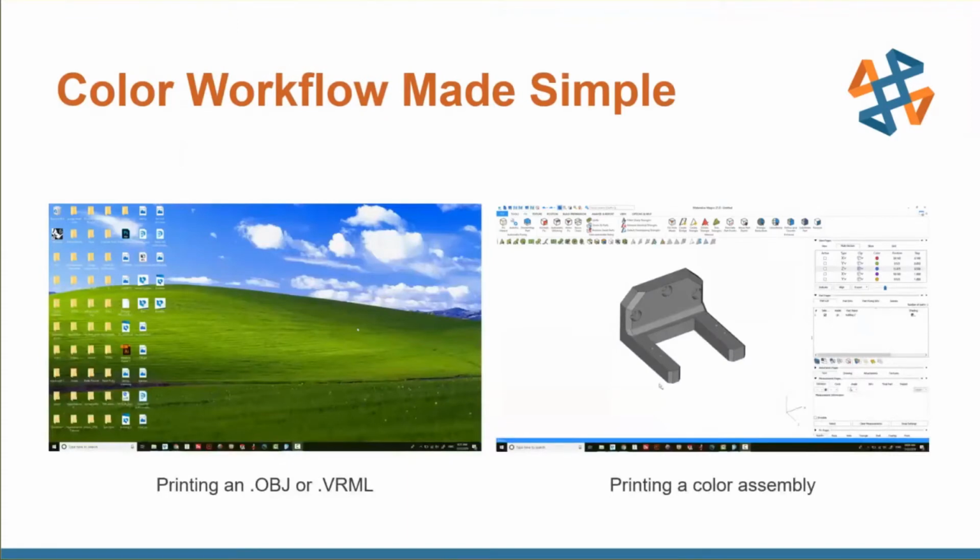So just to have a little bit of a baseline idea of two different versions of the workflow of what we could be doing. In one instance, we can print an image that is wrapped around in a mesh, and that's going to be an OBJ or a VRML format. And then on the other side, we're going to have single shells as an STL or maybe even a native format that we can apply color to within our slicing software.